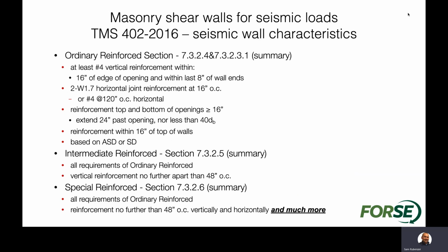So as we're talking about partition walls, I'm going to bounce back to shear walls for just a moment. Looking at some of the different provisions that you have for shear walls, I think there's a couple of provisions that have had some carryover effect. There's certainly a design time, maybe shortly after IBC 2000 came out, when we had a lot of walls that would have been partition walls that participated in maybe some of the shear resistance in a building. We had some of those walls that are kind of in that gray area.